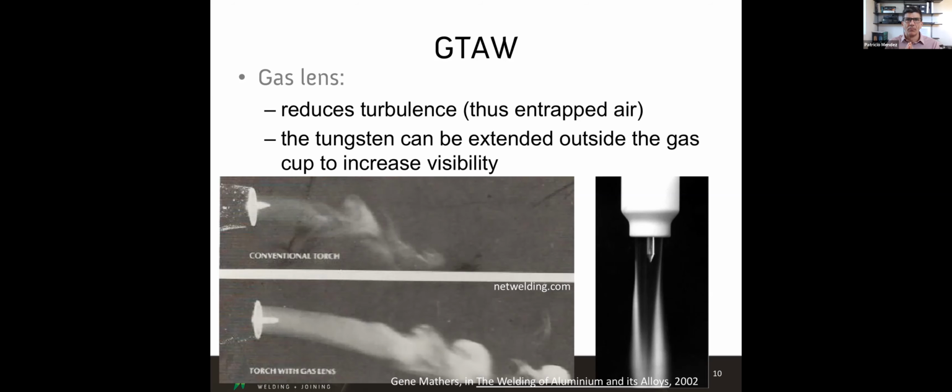And what it does is to kill the turbulence of the gas and have what is called, all of you have taken fluid mechanics, a laminar flow. So what you get to see here is how the gas is coming out quite straight. Laminar flow, that's exactly what we want. And if the distance is too high, then turbulence sets in and we can have a problem.